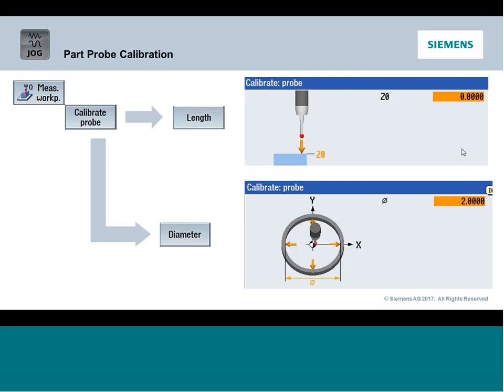The next step, which gets a little trickier, is calibrating the length. And the reason why I find it gets a little trickier is because there's really two different standards of how you set up a machine tool when it comes to tool length compensation. We have what's called positive tool length compensation. That's where my physical tool length in my tool table would actually be a positive value. And that would be a value of the tool from the tool tip measured back to a gauge line dimension. Generally, it's the face of the spindle or somewhere close to that. So that's what we refer to as the positive tool length method.